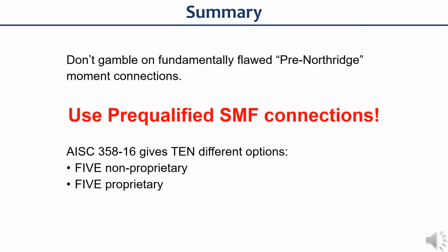Before ending this presentation, let me give you this advice. Don't gamble on fundamentally flawed pre-Northridge moment connections. We have to use the pre-qualified SMF connections given in AISC 358.